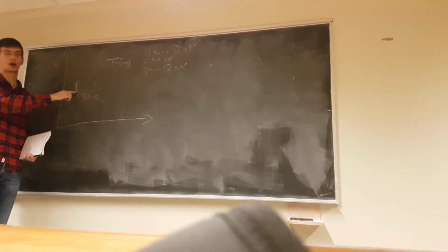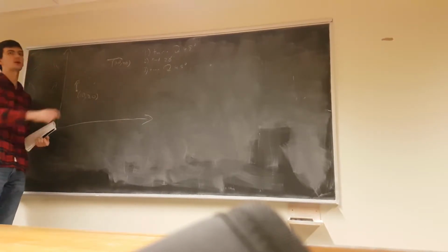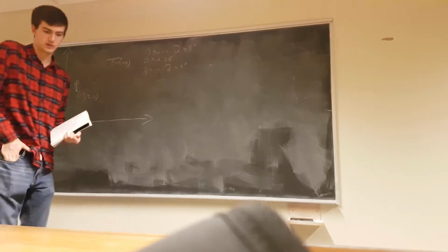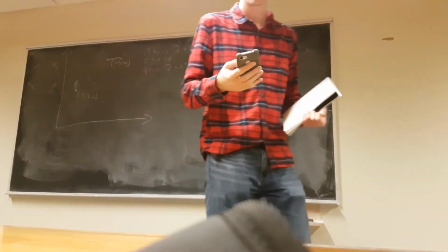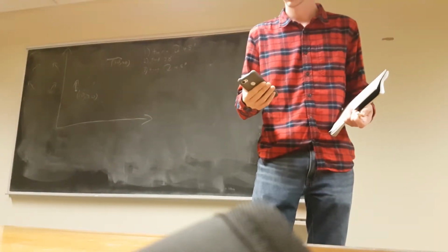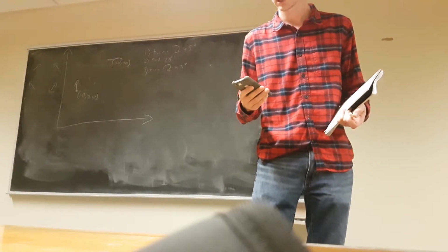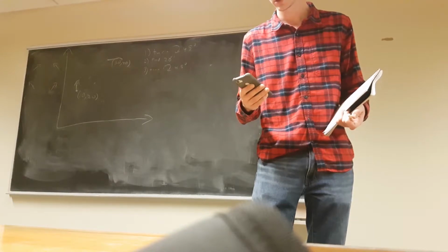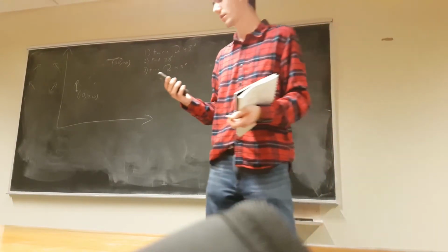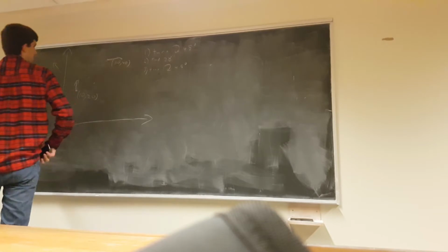Let's say you were half a degree off on this turn, which by the way is impressive in its own right. So you're half a degree off. How far off will you be when you get there, assuming that the straight drive goes perfectly? The answer is 28 times the tangent, in degrees, of 0.5, which is about a quarter of an inch. Okay, that's not too bad.